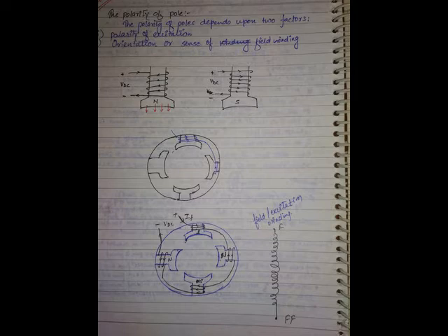Hysteresis loss formula is there. In that formula, it's like this: hysteresis loss is equal to some constant kh into Bmax to the power 1.6 into f into V. V is the volume. We will discuss the formula later in the losses topic. What I want to convey is, there is 1.6 here. This is actually x.